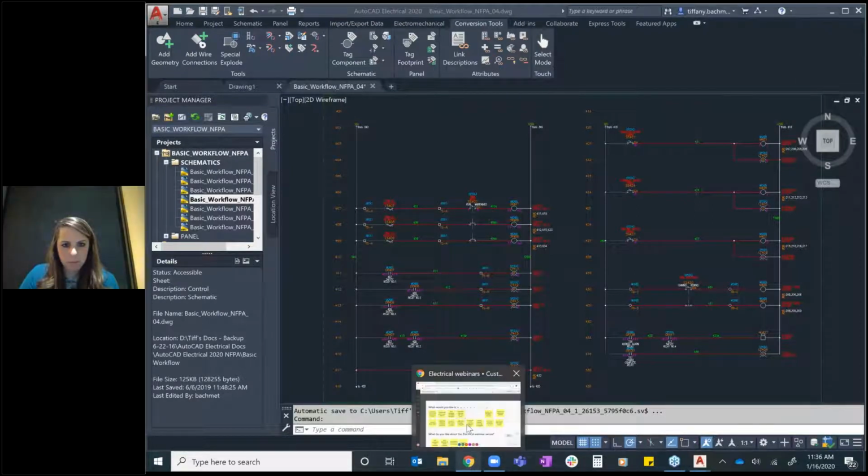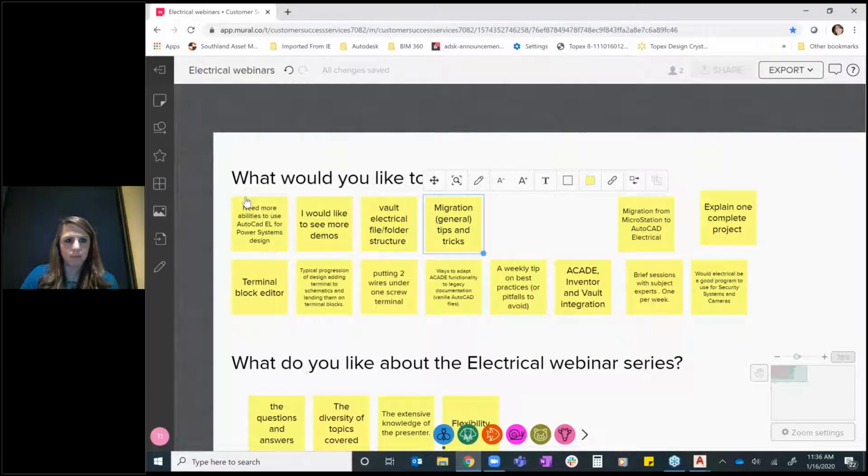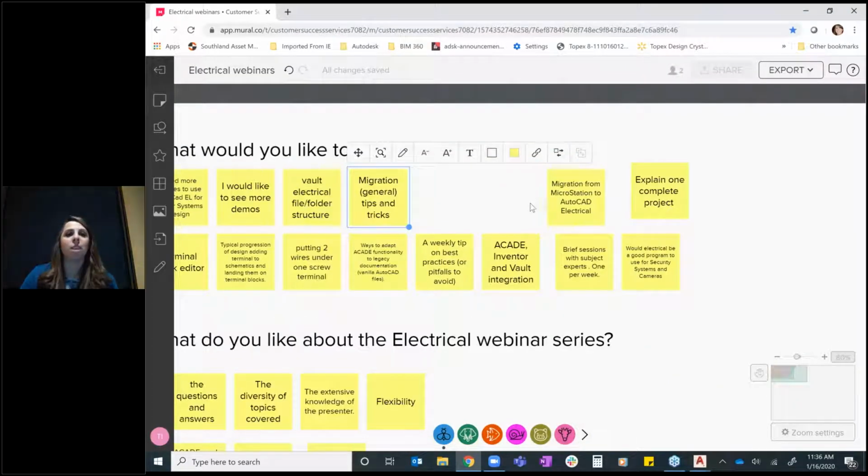So Bill mentions, thank you for the tips, and that he's using the import of DGN command in ACAD. Oh, he is using the import DGN. Okay, so that's one of the migration tips and tricks I would have talked about. Again, everything on that conversion tab, in all of my electrical classes, I would say don't touch this tab. And there's a little bit of mixed feelings on that. If you ask other experts, some will say, oh, you can do it. But again, most of us would say not for copying over drawings over and over again to reuse. Build that as a clean drawing set in electrical. You would use that really only for a quick cleanup of something that's as built that you need to maybe add a couple things to. So really great questions. Thank you for that.